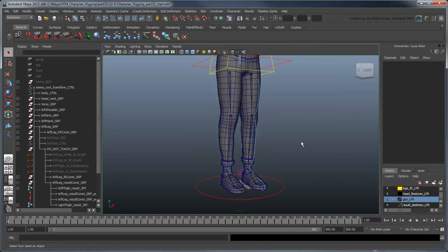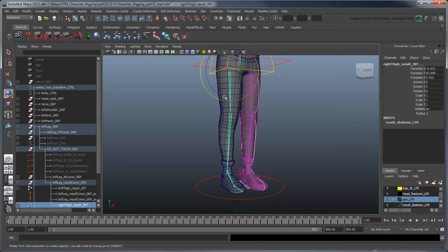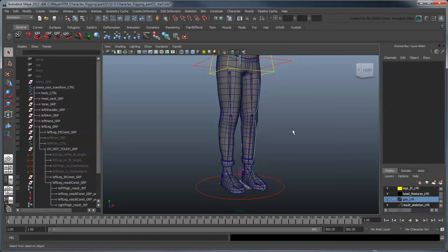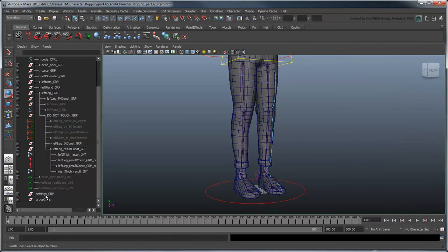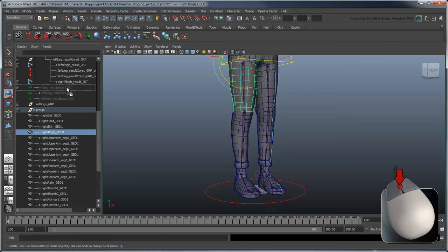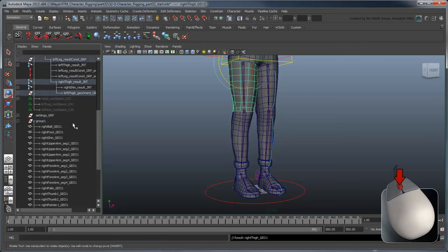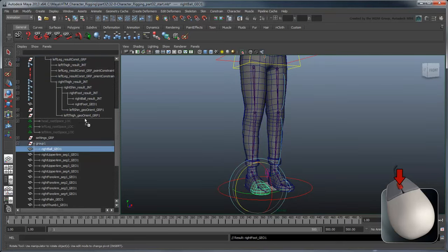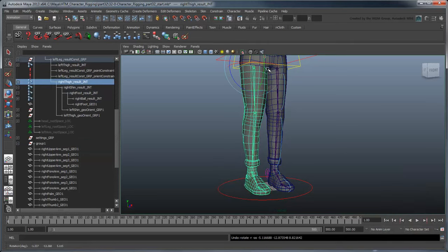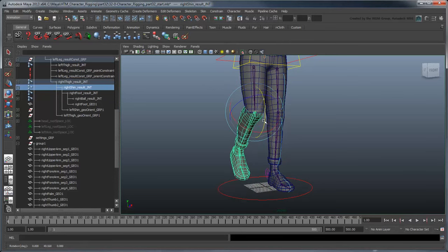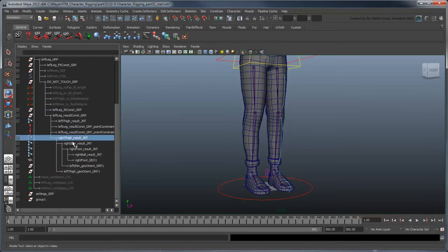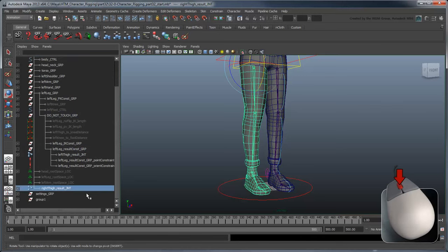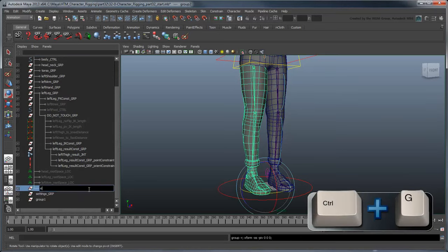The new joint orientations facilitate the mirrored rotations we want without inversing the scale. Now parent the mirrored leg geometry from before to the appropriate parts of the leg. Reparent the joint chain under the Emma-Root transform control, and then group it into a right leg group.